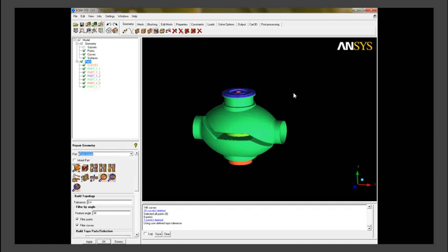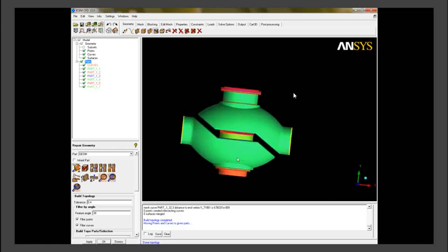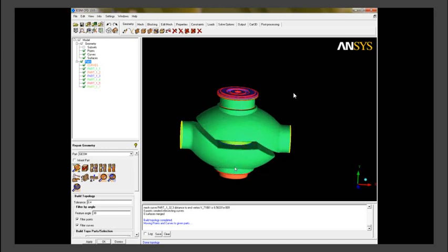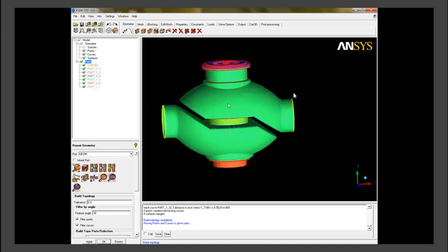Now we will deal with the bigger external valve geometry to create inlets and outlets. We need curves there to create our surfaces. So we are using the build topology option to create the bounding exterior surfaces as shown here for the inlets and outlet. The build topology option will create curves again, that is, the external curves for this part. We will use these to create surfaces.